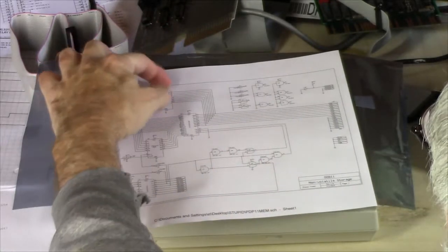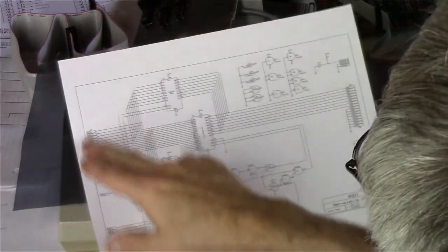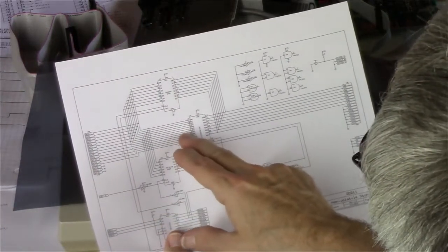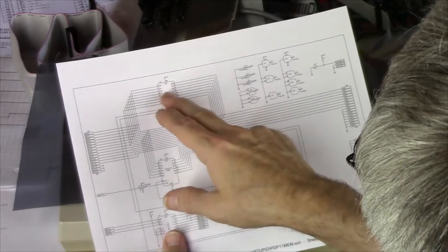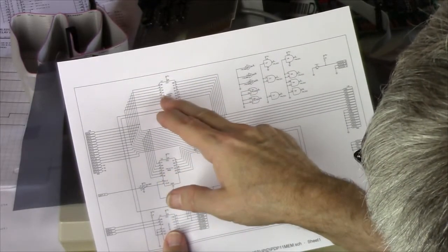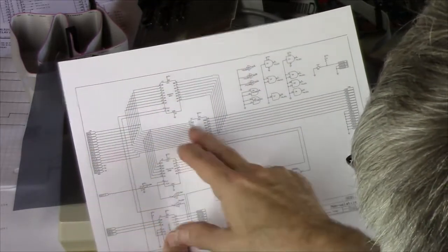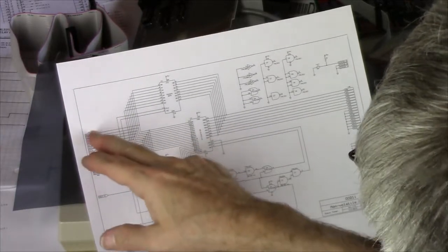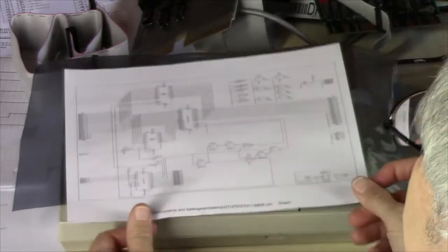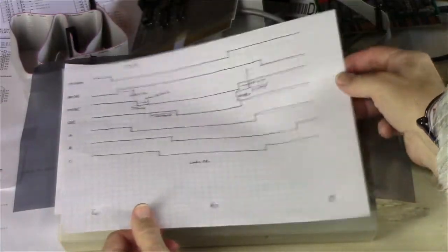because we have to save that data because we only have the single input bus here to the device. We have to save that write data into a buffer because when we are performing the write, what's on that bus is the address.